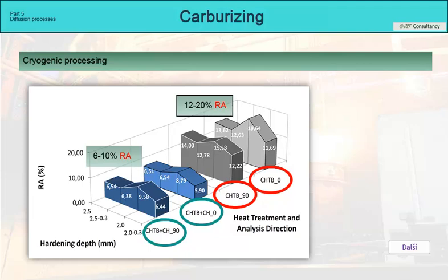In practice, freezing times usually range from 2 to 4 hours at temperature. However, since the decomposition of residual austenite and its transformation into martensite occurs only by carbon diffusion in the crystal lattice, these processes are slow, and this fact is further enhanced by the low freezing temperature. We cannot therefore expect to reach zero values. We would have to significantly increase the freezing time to times of 24 hours or more.